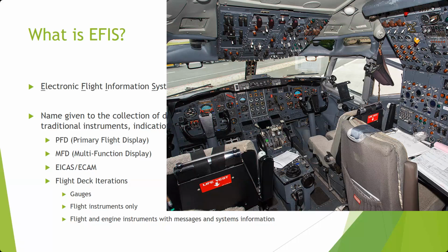So different things like that use that tactile feel. Up top, you have switches that are guarded. In this case, they're guarded in the flight position. So if you bump that switch, one, it's not going to allow you to switch it, but also you're going to have to flip the guard down and flip the switch. That should make you think there are two steps now. Maybe there's a reason it takes two steps. Or some of your switches where you have to pull out on them to move them, same thing. You have to pull and then switch it. You can't just switch it, right? That's because you don't want to bump them into the off position or into the on position.